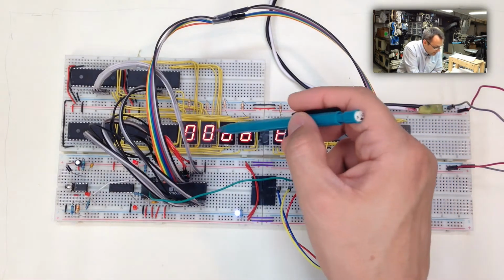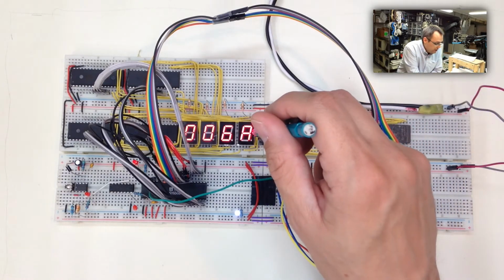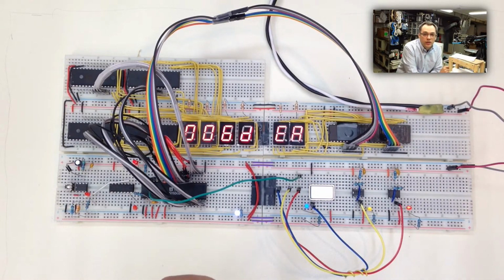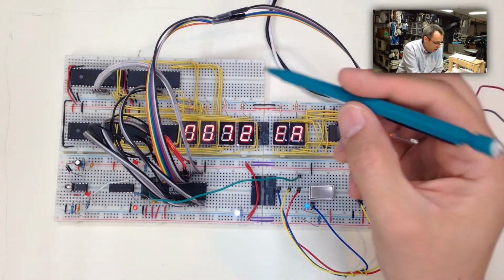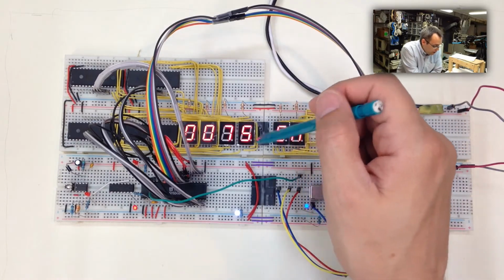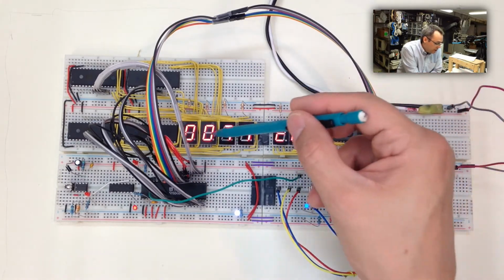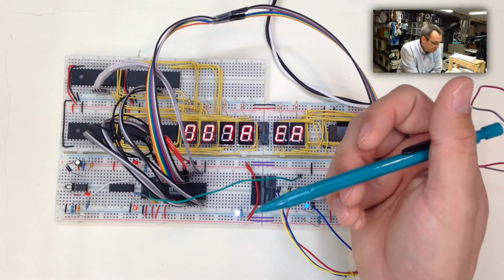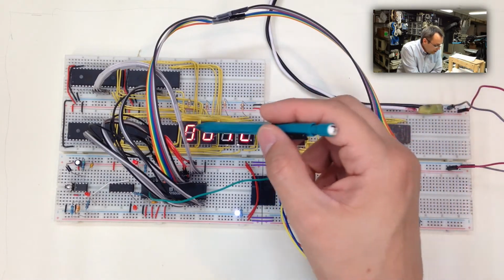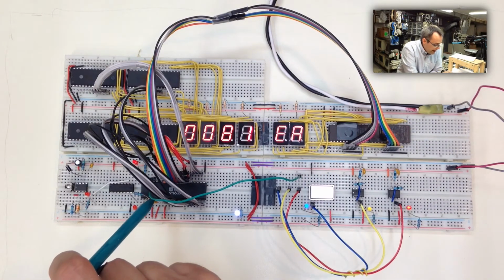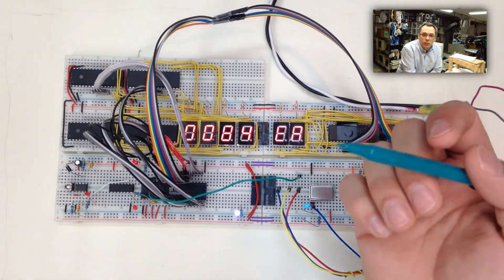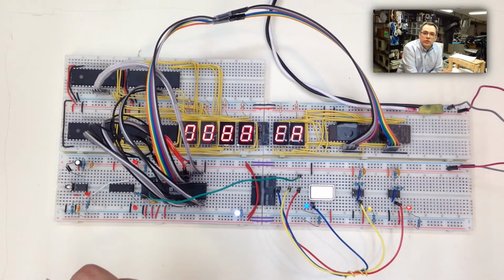The other problem we had is this thing did not start where the reset vector said it should have been. The reset vector being like FFFE and FFFF or something like that up at the high end of the memory space, which should have told it to go to a specific memory location, but it just started at 0 and started counting up. The reason why that happened is because the CPU starts in an unknown state. If it doesn't set up correctly when it boots up, it usually just starts executing from 0000 and just cycles up.